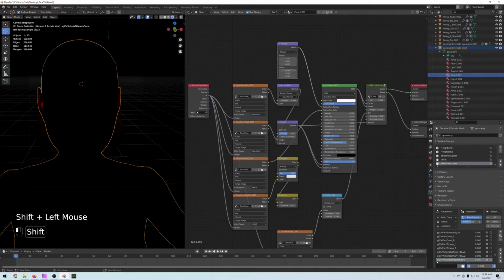So like I said before, if you set this value too low, the light will never penetrate. The red, green, and blue values are coming into the mesh, but they never go through it because they're only going through 0.0001 meters or millimeters, whatever the measurement is, and they're not exiting.